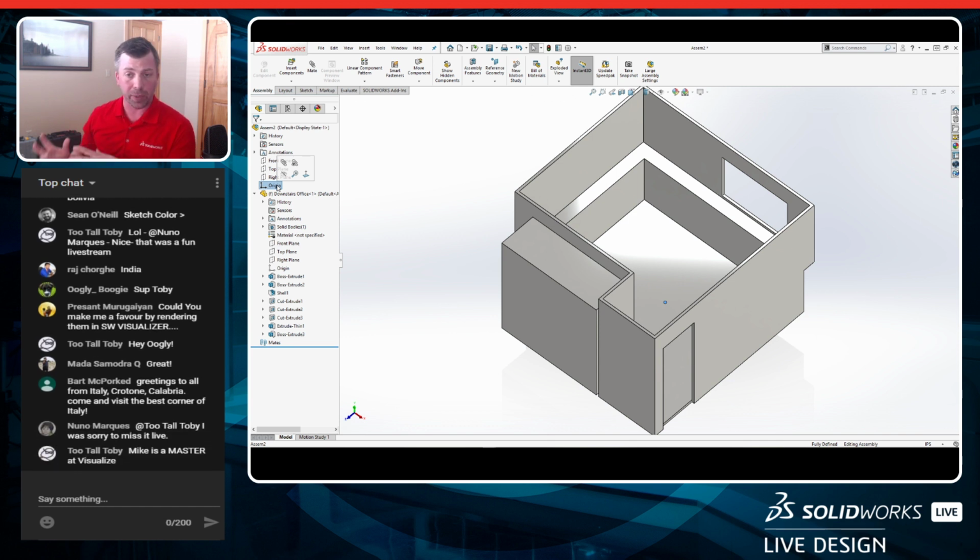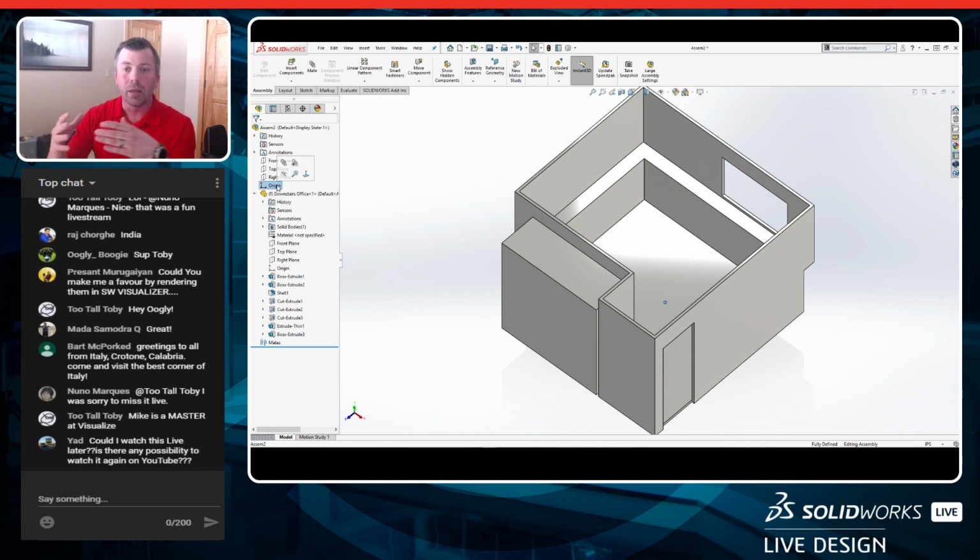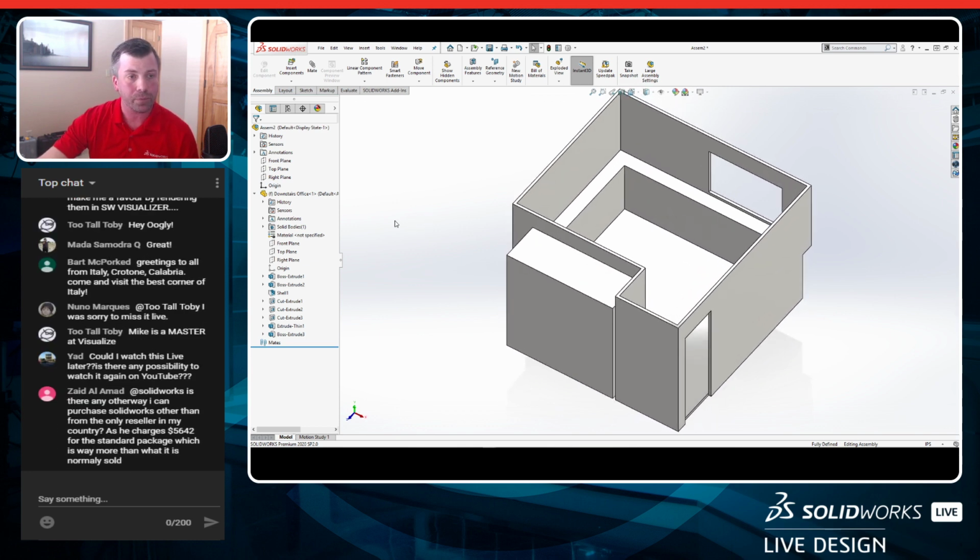So if I go and add something later on, I can use this in-context approach, make the design, and I don't have to worry about mates necessarily as we start to lay out the office space. Now, it's just the way that I'm going at it. There's multiple ways you could do it. You could do a top or a bottom up approach where you design the desk separately and insert this and mate it into place. But I kind of wanted to see this organically unfold as we were designing the desk. So that's why I chose the top down or in context approach to it.